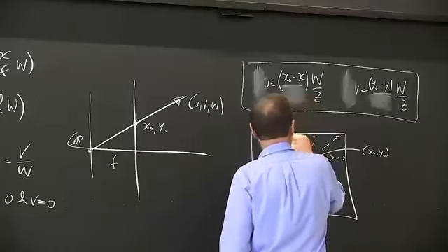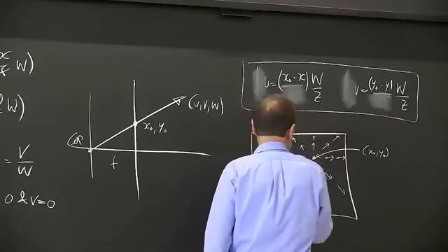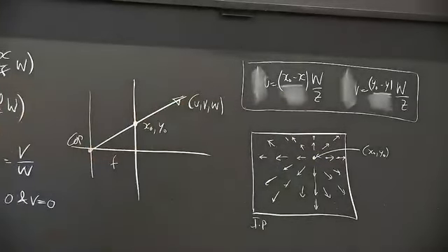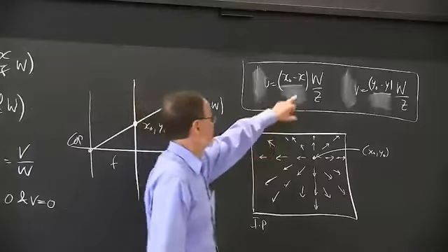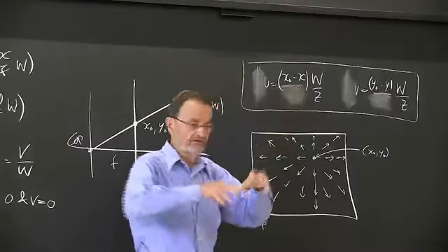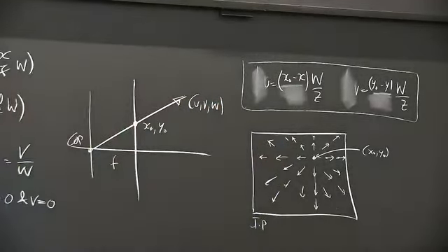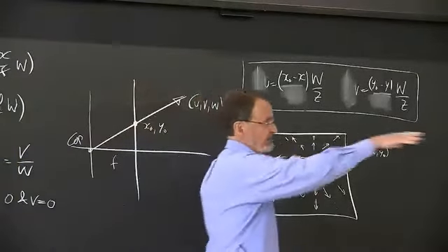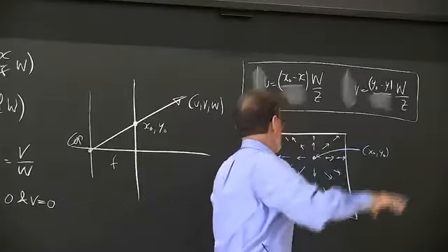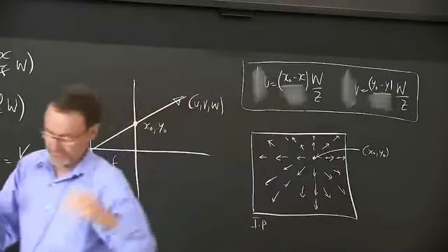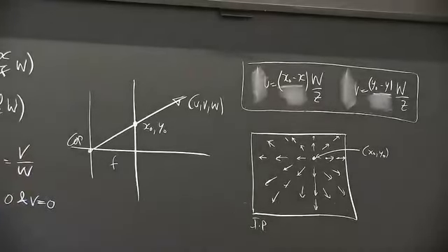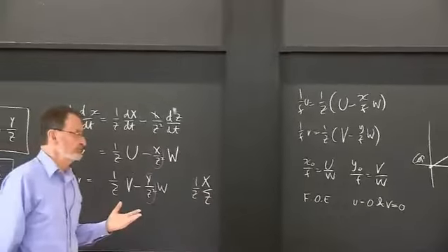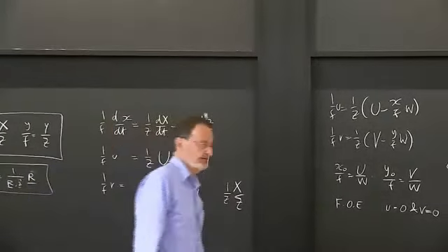And I think you can see that we're going to fill in this whole diagram, this little vector diagram, with arrows that are pointing outwards from the focus of expansion. That's what this equation says, that all these vectors are radiating outward. And that's why it's called the focus of expansion. So I'm moving towards that wall, and this is the place I'm actually going to hit. I may be going at an angle, but my whole image is looming. It's zooming outwards, which is a useful clue, useful cue for measuring distance and velocity.